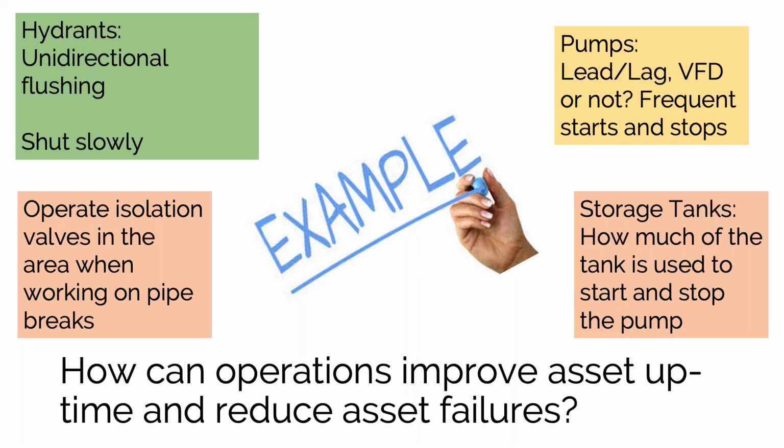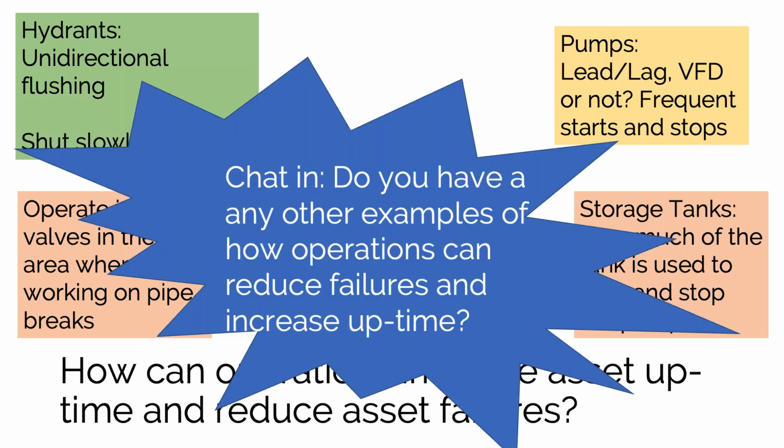With storage tanks, like how much of the tank is used, presuming you start and stop your pump based on levels in the tank, and not everybody does, but if you do, you might change what that level is, so maybe the pump starts and stops less frequently. So it's things like that that can really help you.